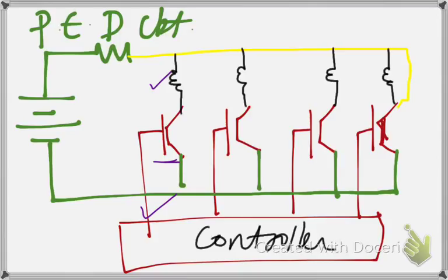So it actually limits the working of the circuit, because the speed of this stepper motor is dependent on the frequency of the circuit. If the current is not reaching its peak value at the proper time, then that is going to be a problem. To eliminate this, we have this series resistance connected over here. This will help the inductance reach the peak value of current in the proper time.